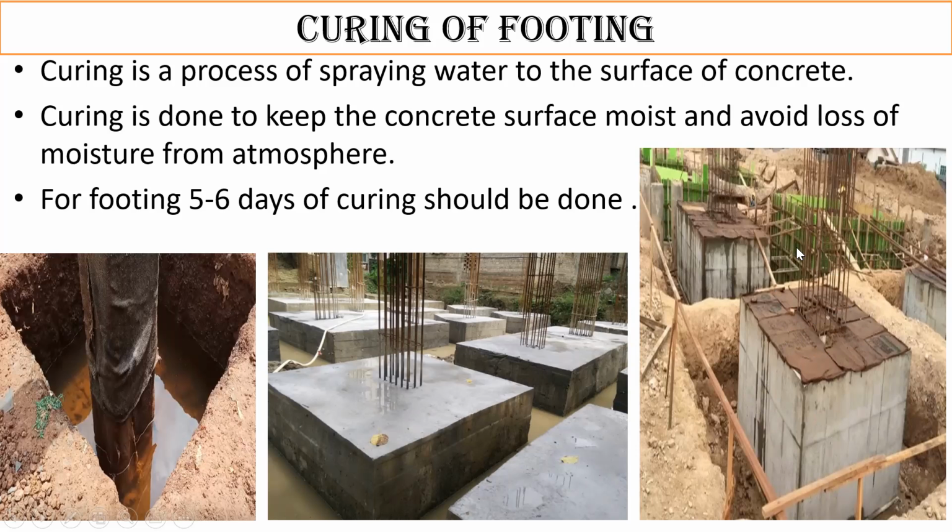So even if sunlight comes, it's going to make use of the water, I mean, the water is going to get evaporated which is at the top surface, not the water which is present inside the concrete. So that water is actually your designed water that is required for the complete process, for the hydration of the concrete. So this is the main idea of doing the curing.